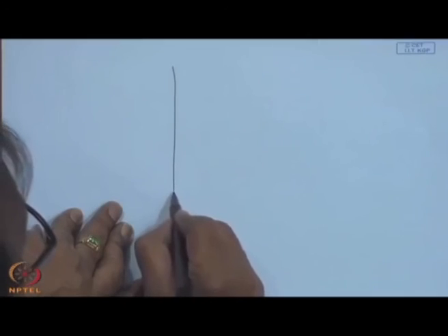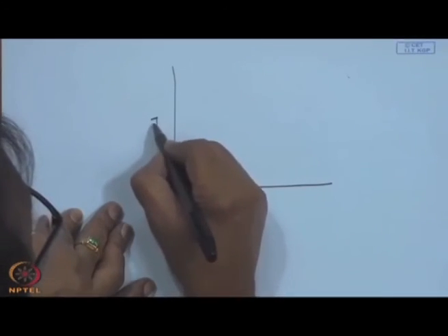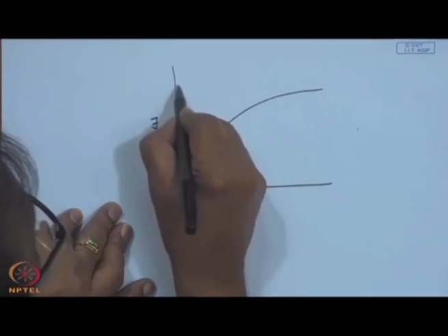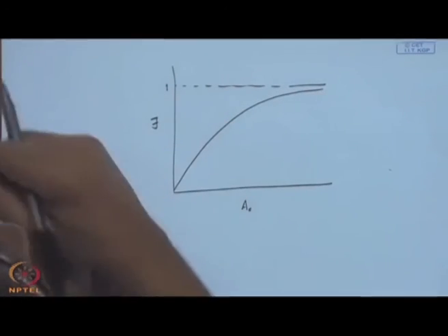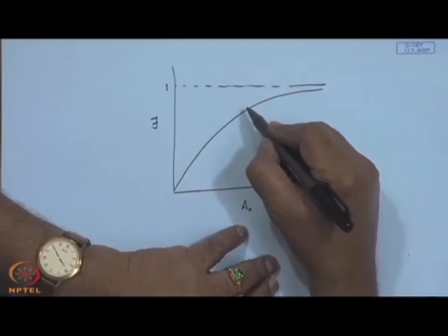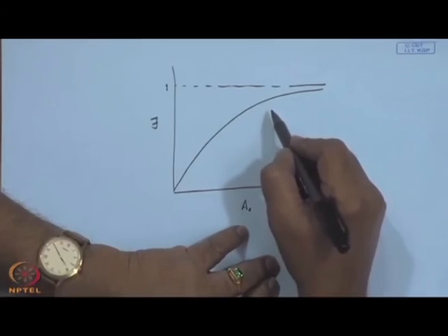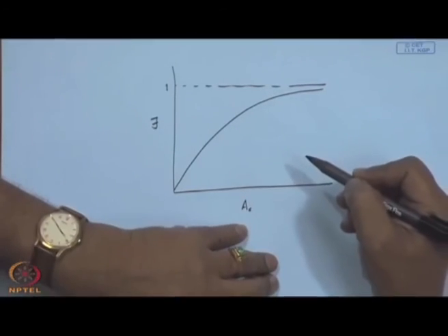This is the sum and substance of the design methods, which you have to make 12 monthly calculations. However, even for a yearly prediction by hand calculation, it is a tough situation. So, one would go for a little programming, but then once it is done, it is quite easy to calculate the yearly solar load fraction. That is, ultimately by making 12 monthly calculations, we are in a position to get area versus solar load fraction, something like this. This is unity, and I can do whatever optimization or whatever studies one likes to have by changing the system parameters, either the storage or the flow rate or the heat exchanger size, location, area of course is the main thing, and collector parameters.